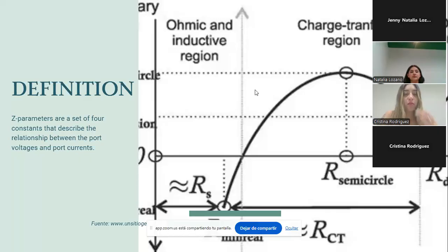To make this more tangible, let's consider an example. Imagine a simple T network made of three resistors R1, R2, and R3. R1 is in series at the input, R3 is in series at the output, and R2 connects the midpoint between input and output. This forms a classic T configuration. We can calculate Z parameters for this network using basic circuit analysis.